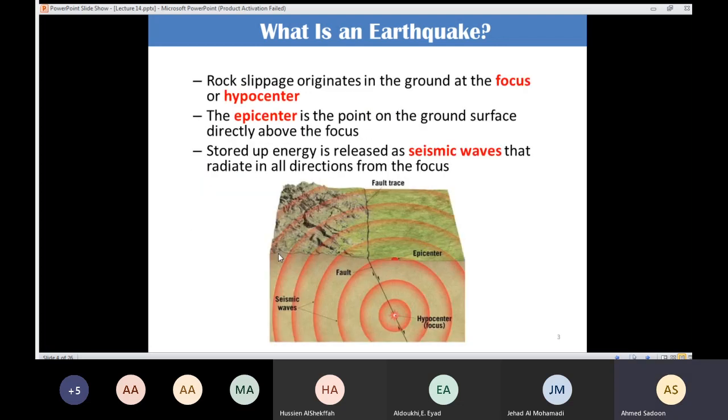In the beginning, we are going to face frictional resistance. And during that time, because of the frictional resistance, we are going to build up stress. Because we have forces, one block wants to move past another block, but because of the frictional stresses, that movement cannot take place, which means that we have a lot of stress. And when the stress passes that frictional resistance, then the slip will initiate.